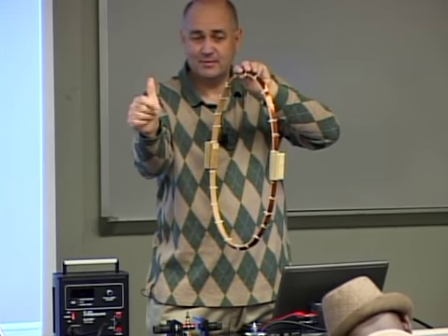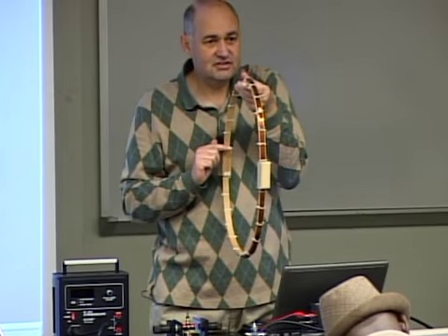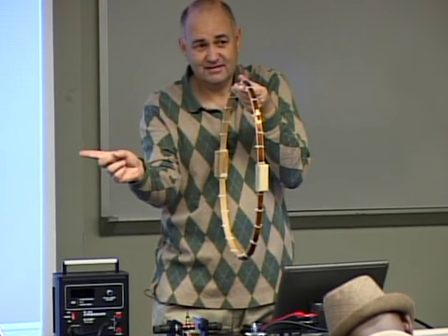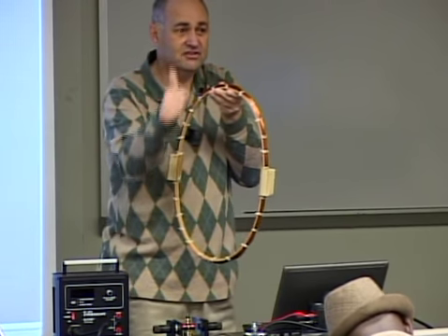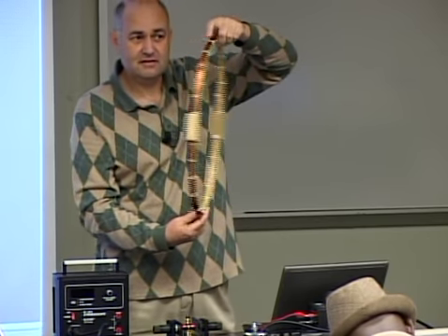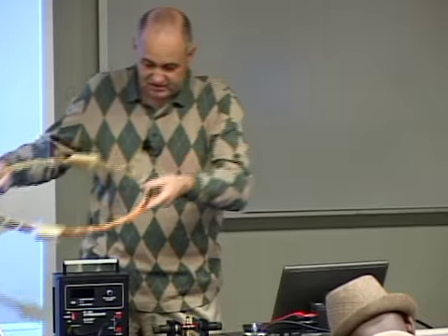Magnetic torque is up. The loop turns. At this instant, the commutator changes the direction of the current, flips magnetic moment. Magnetic torque is still up. And this way, we make a motor, which is a DC motor, and then it is supposed to rotate.